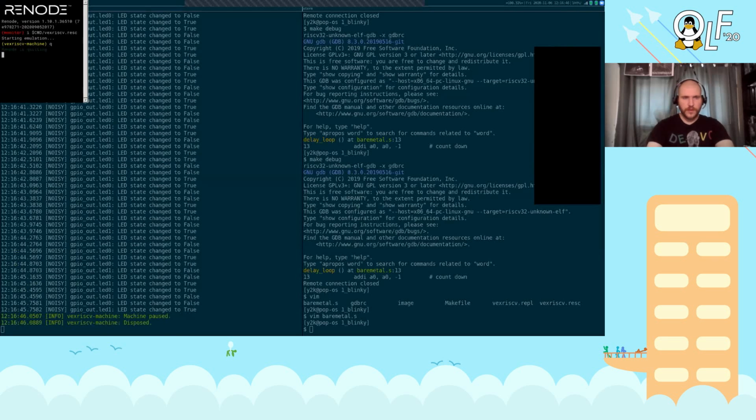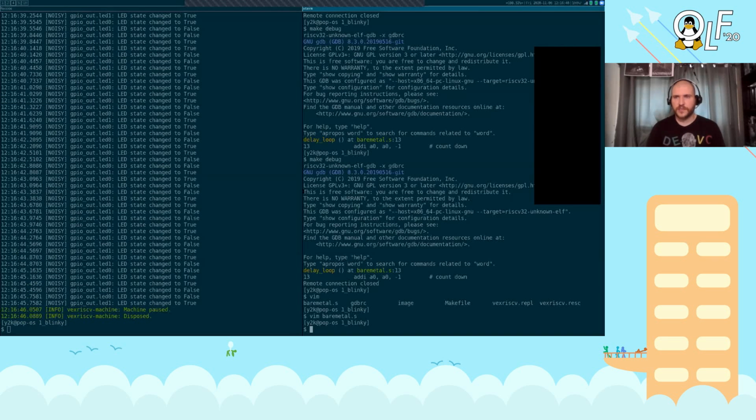And so as you can see, it's a very fast iteration environment where we can go through and change your software, change the firmware, reload it into hardware and test. So if you're building something substantial, this is great. You don't have to wait, make some image, flash it onto a chip, and then get some feedback. And then how do you debug? Typically you'd hook up an actual hardware debugger or some sort of JTAG so that you can get GDB on the real hardware. But for the first 95% of integration, it would be really nice if you could do it all on your laptop, especially if you have a fast emulator.